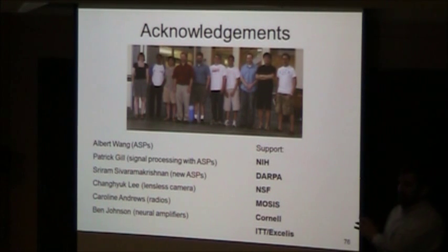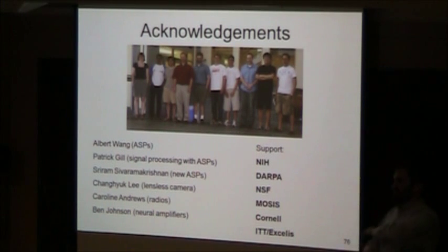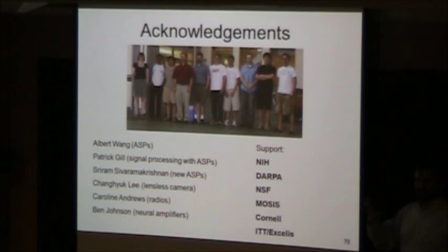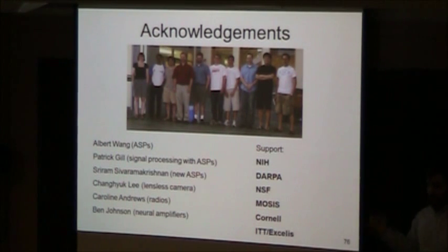So we've done both. Typically, in the process we were working in, there were 5 good metal layers for this. So we had a lot of choices of metal layer combinations, and we ended up picking a few that were good. There are some constraints in this. This actually doesn't work very well if you don't have at least about 5 metal layers to give yourself enough freedom. And then wavelength. Yes, wavelength is an issue because the Talbot effect is wavelength dependent.